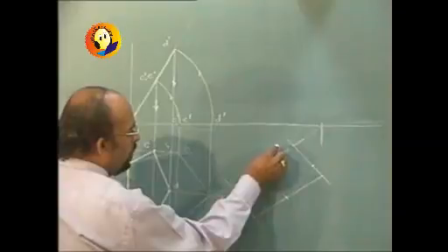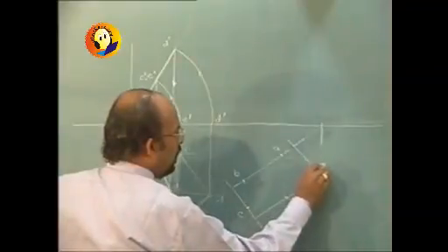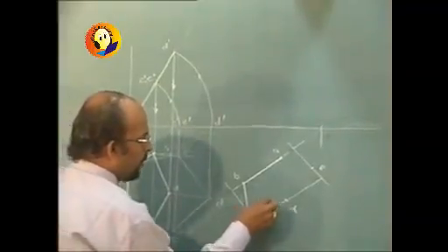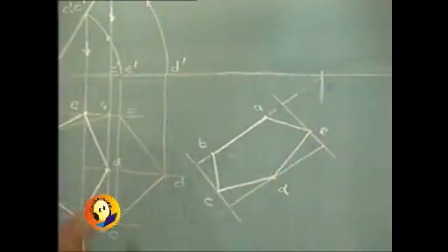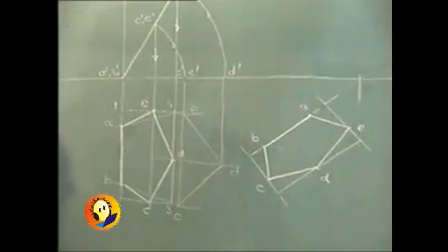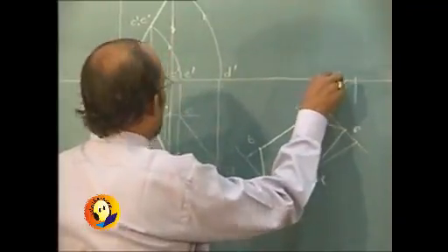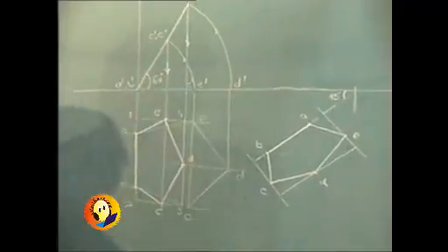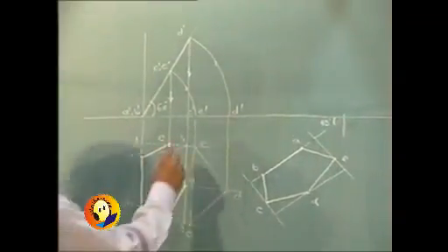So we have got all the points using rectangle technique, which are to be joined by the full and final lines as such. This is the rotation of plan, again by 45 degrees in this case, as is given in the problem. This angle is 45 degrees. The angle through which we had rotated the line view, that angle was 60 degrees. So this is rotation in one view, is movement parallel to XY in other.